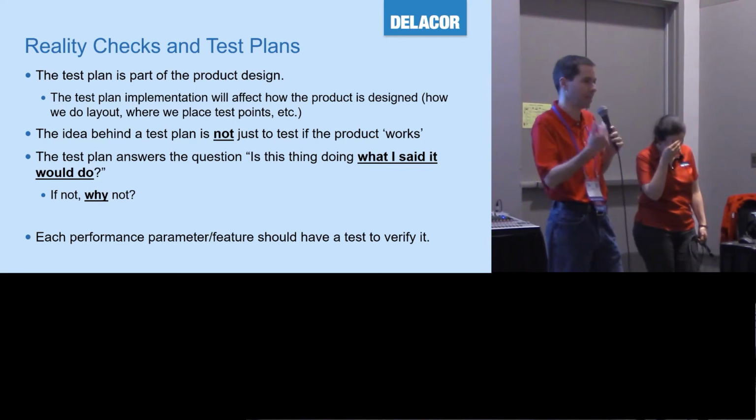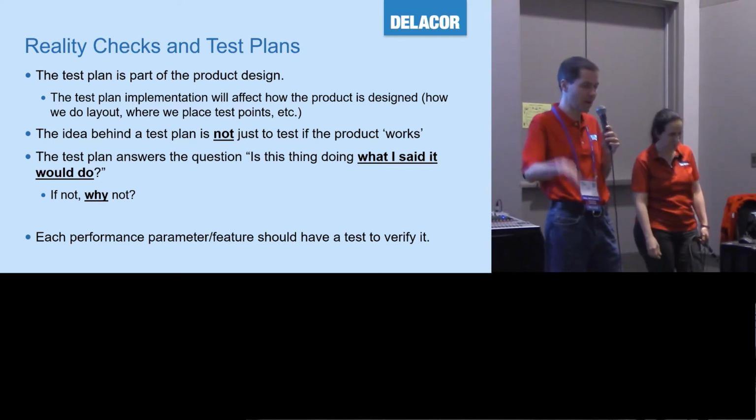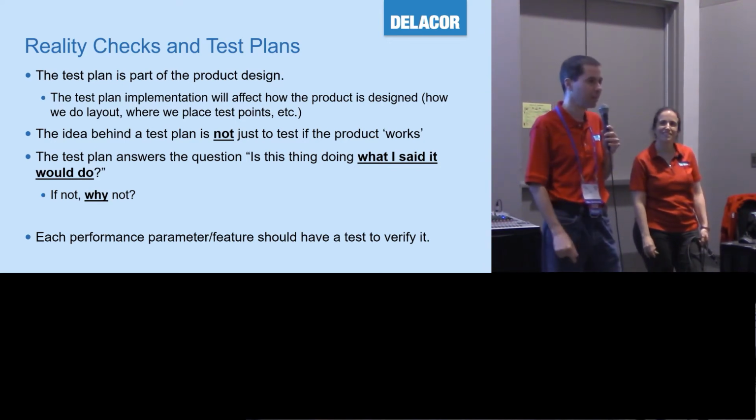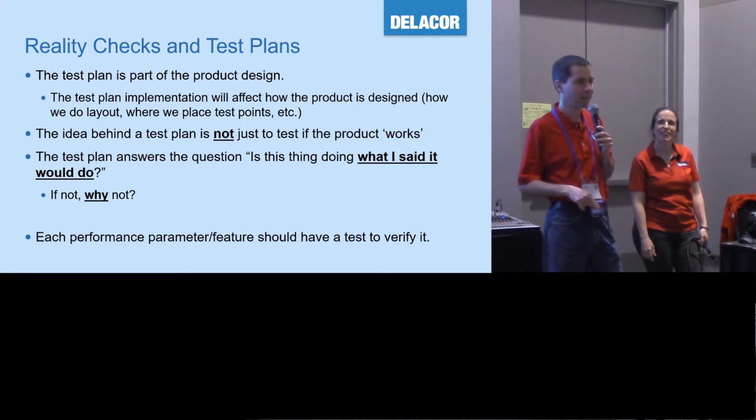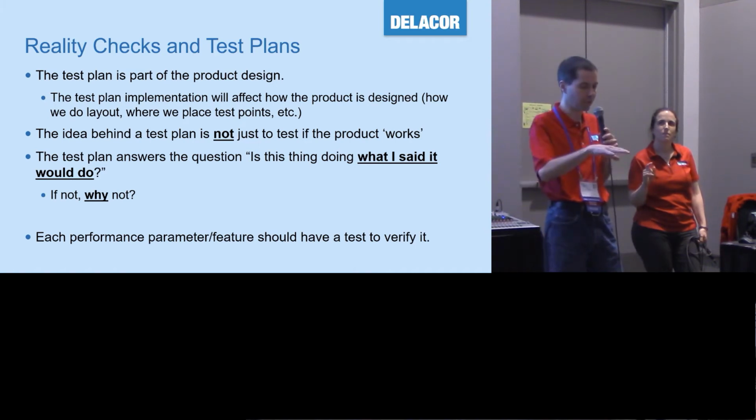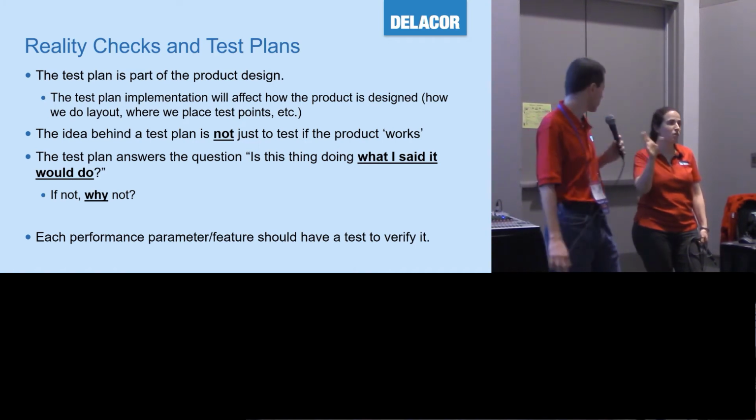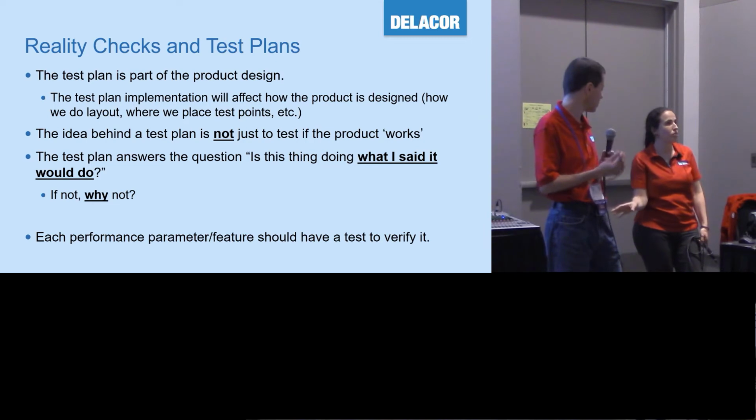You're going to read the codes out of the ADC, and you're going to look at, does the linearity match what I put in, and does it agree with what the datasheet says that it should be. And especially something like linearity that you can affect a lot by how you lay out the board, how you do bypassing. And the reason for that is because linearity was the thing that you were interested in, right?